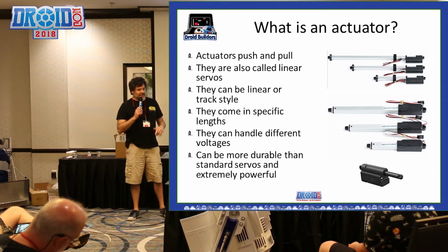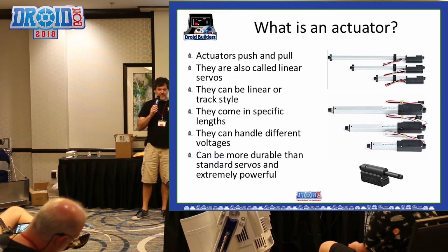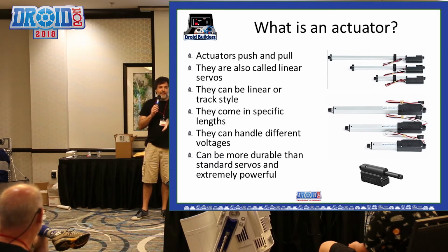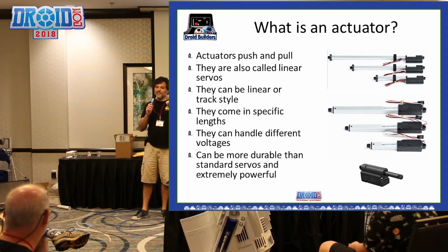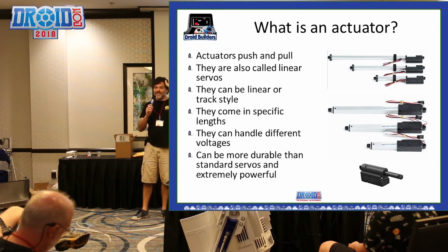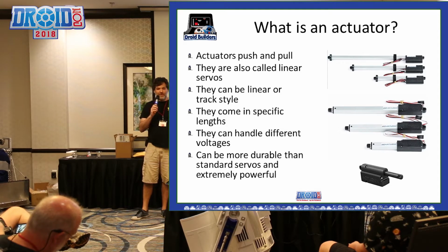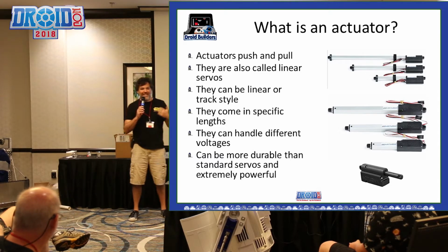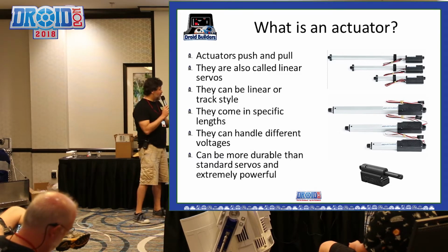I don't have to tell R2 to move this thing so many inches and stop and then zap. I just turn it on and the current feeds the zapper all the way out, and when it hits the limit switch, it stops. And I know how long that takes, so I put a little sleep command in there. It says sleep for 3 seconds and then zap it. And then I do the same thing in reverse to bring it back in. So it's very, very simple to make it work.